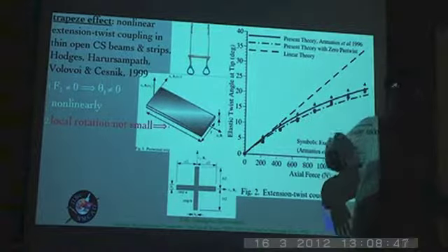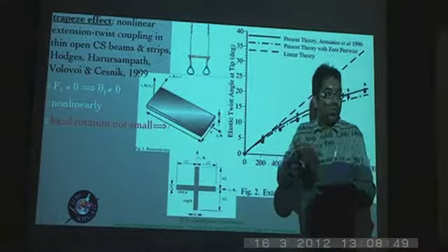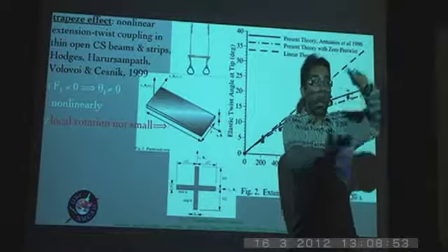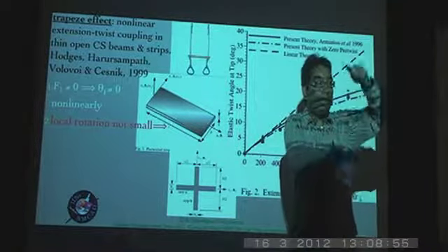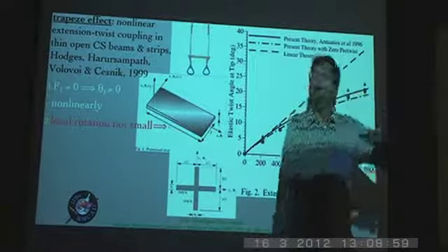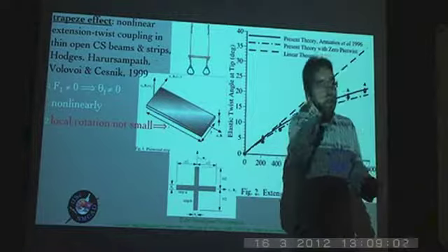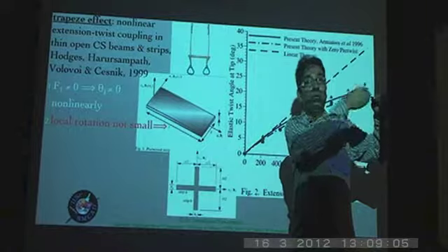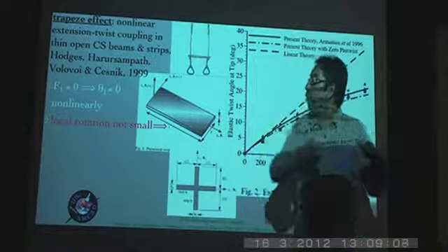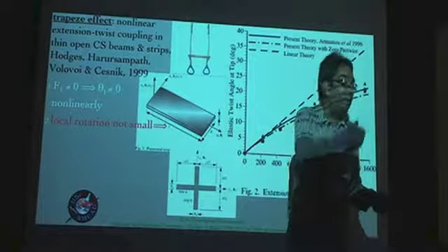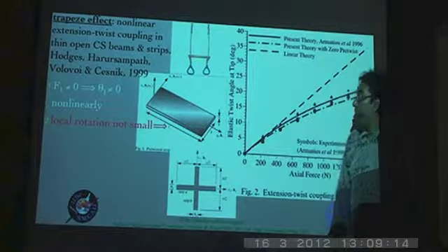Unlike in the previous case where W2 and W3 by themselves were directly influencing that, in particular W3, large values of W3 were basically causing the I2 to reduce and therefore the bending stiffness to reduce. Here what is happening is that there are local elements in the cross section which are turning. There is local rotation, and those local rotations are not small, and that is what is in turn causing this S12 to be a non-constant.